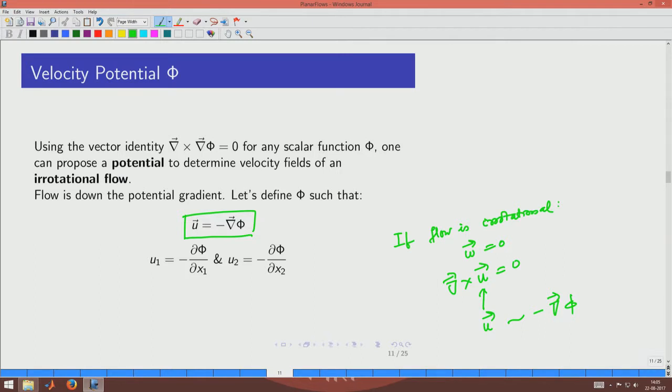So, we have one more way by which we can generate the velocity components, that is by using the velocity potential. The way velocity potential is used to create the velocity components is given by this expression. You can see that this is different from the stream function expressions. The indices are matching here, and in the case of a stream function they will be opposite.